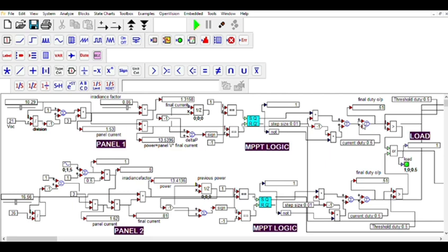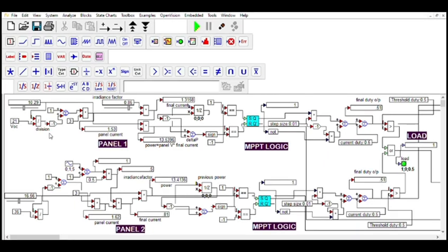This video presents my project, Smart MPPT (Maximum Power Point Tracking) System using dual solar panel and load switching. The Altair products I have used to model and test logic-based MPPT control are: a slider to set manual irradiance of panel 1, a sine wave generator to simulate sunlight variation of panel 2, constant blocks to define open circuit voltage, threshold values and initial values, gain to scale the irradiance or step changes like 0.01, multiplier blocks to multiply two